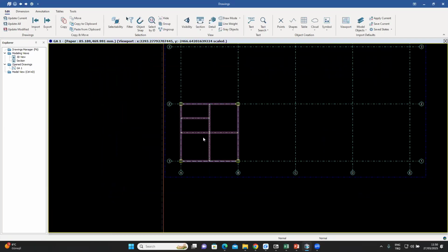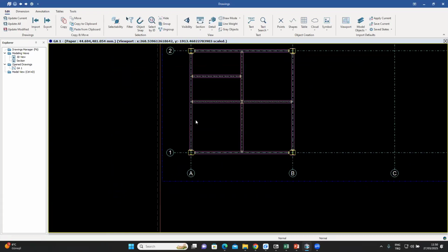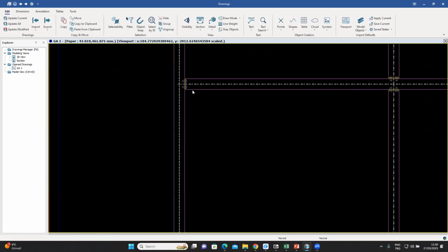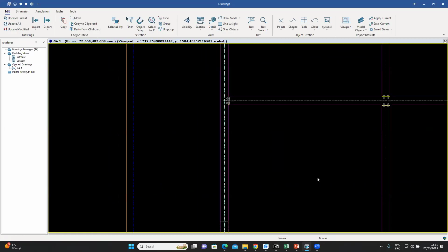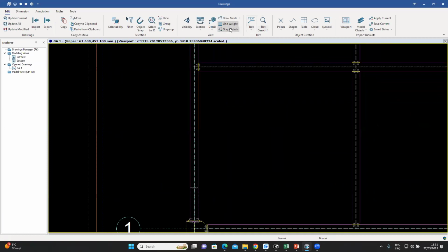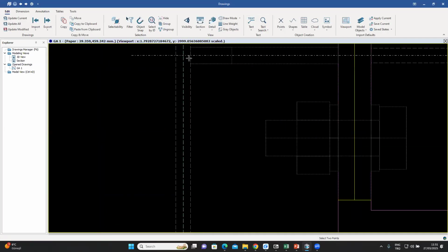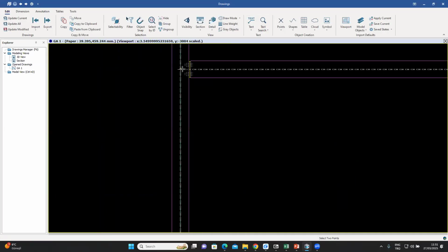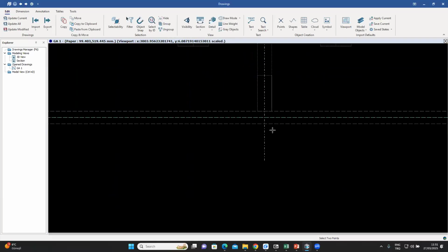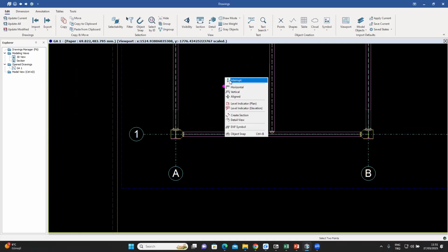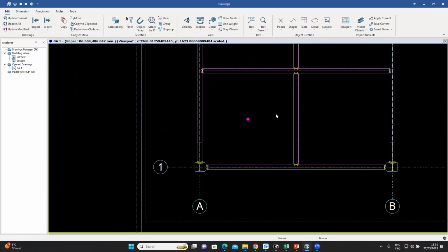So, for example, if there's an electrical fixture, just as an example, and it is located somewhere in the middle of this, and you don't have a point to snap to, you could go to your points and go to dividing points, select this one, and then zoom out, select this one, and create this kind of a temporary point, which you can see on the screen over here.